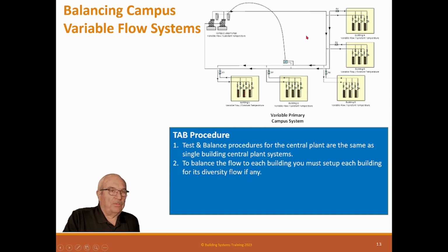Now the one problem with a system like this is you're going to be screwing up every building as you go. Normally when you see a system like this, these are existing buildings, and this is a new building. So you have to try to get balanced flow to this one without screwing up these buildings. And it's almost impossible to do, because you need these valves all open. You need these valves open to be able to do the flow, which means you've got to screw up every building. So that's why you don't see many systems like this.